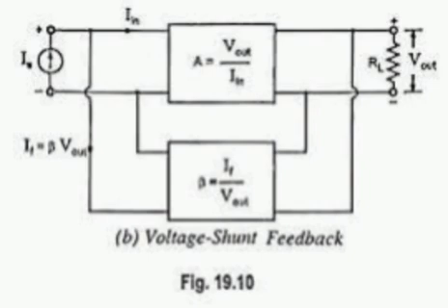Voltage series feedback: input voltage, output voltage, gain is AV, RI increases, R0 decreases. Current series feedback: input is voltage, output is current, gain is denoted as GM, input resistance RI increases and R0 also increases. Voltage shunt: current is input, output is voltage, gain is RM, so RI decreases, R0 decreases. Current shunt feedback: input is current, output is also current, gain is AI, RI decreases, R0 increases.